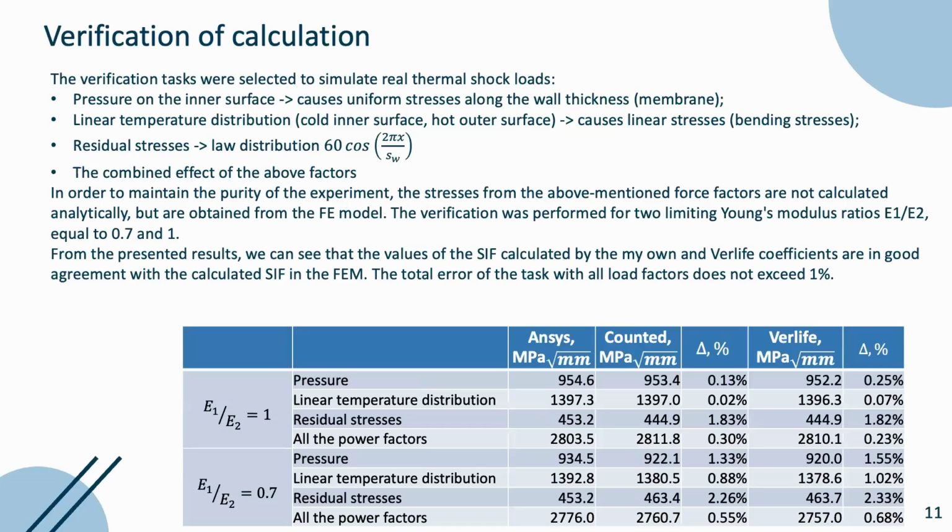Our shape factors were verified. For verification, we selected loads to simulate real thermal shock: pressure on the inner surface, linear temperature distribution, residual stress, and all loads combined.